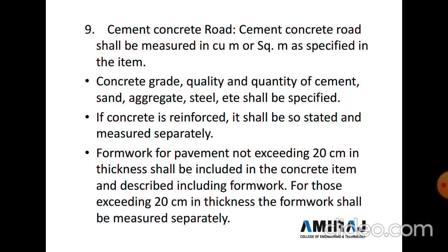And the last point is cement concrete road. Cement concrete road shall be measured in cubic meters or square meters as specified in the item. Concrete grade, quality and quantity of the cement, sand, aggregate, steel, etc. shall be specified. If the concrete is reinforced, it shall be so stated and measured separately. Formwork for pavement not exceeding 20 centimeter in thickness shall be included in the concrete item, and described accordingly. For those exceeding 20 centimeter thickness, the formwork shall be measured separately.